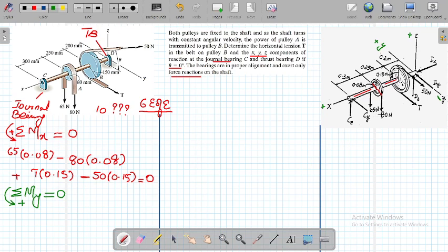And the same with this 80 Newton force which is acting along the z-axis, same sense, and the moment arm again will be 0.25 meters plus 0.2 meters, along the x-axis. So forces along the z-axis, moment arm along the x-axis, the rotation will be about the y-axis.